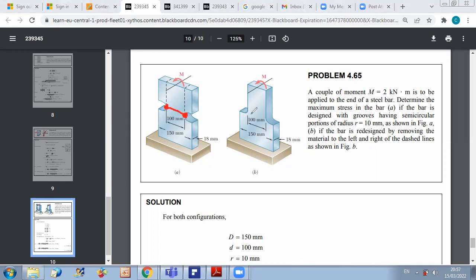First, I consider I have a rectangular section. I treat it normally as we used to do, but I should keep in mind that I have another factor, which is stress concentrations that will increase the value of calculated sigma. I should multiply the sigma by K, which is the factor determined experimentally, and I will find it now from the graphical chart, which is available for me.